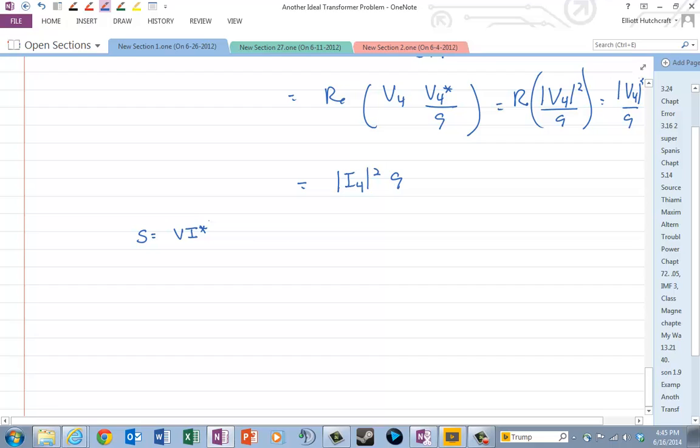The real part of that is the average power, and the imaginary part of that is the reactive power. But this is the formula when V and I are in RMS. The formula for complex power when they are in peak is 1/2 V I conjugate.